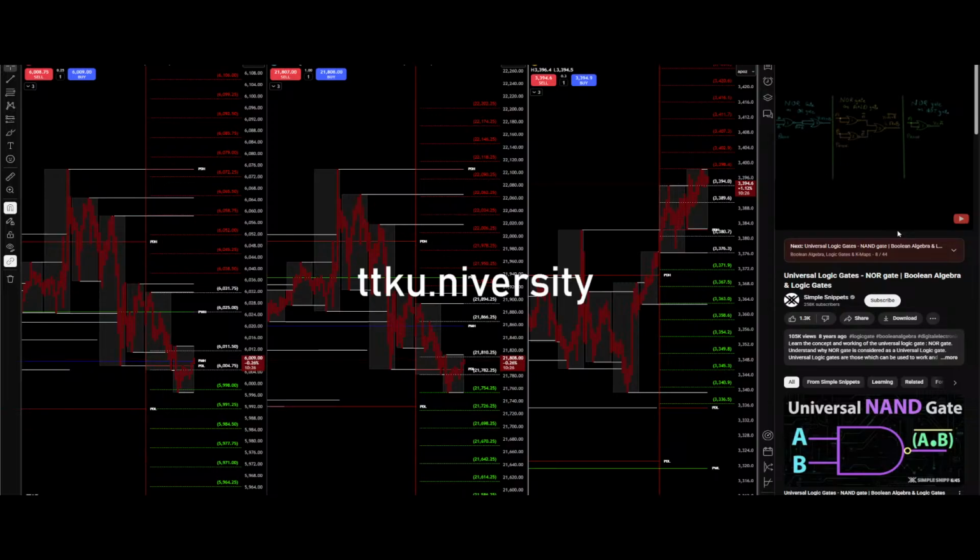Let's prove it. Now here you can see that there are two gates and both are NOR gates. Number 1 is over here and this is number 2. They are connected to each other in such a way that the output of the first gate is the input to the second gate. So let's see what the output of the first gate is. Now, the output of the first gate, as we know, is a simple NOR operation. So we have (A or B) the whole complement. Okay, so now this is again fed in as input to the second NOR gate. So here we will have (A or B) the whole complement, and again (A or B) the whole complement.